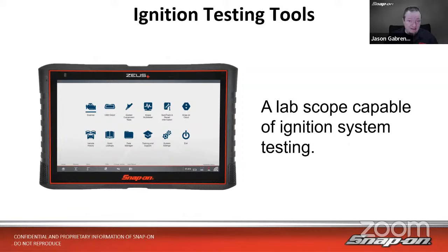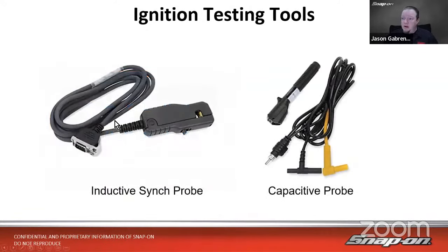Also, I get asked this quite a bit when it comes to ignition testing with the Snap-on scopes. You do not need an attenuator in line, just because of how our probes are set up. It's a very small voltage being fed to the tool, because it's a capacitive pickup, and it's a low voltage. It's able to pick it up and convert it into a signal that translates into 10,000, 15,000 volts, whatever. So you don't need to worry about attenuators. Get that question a lot.